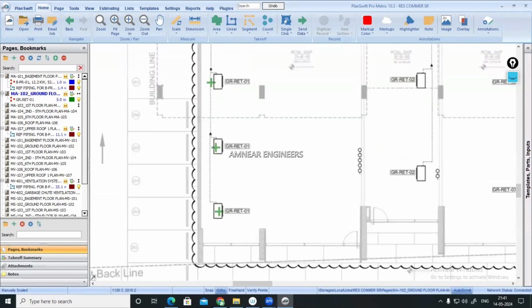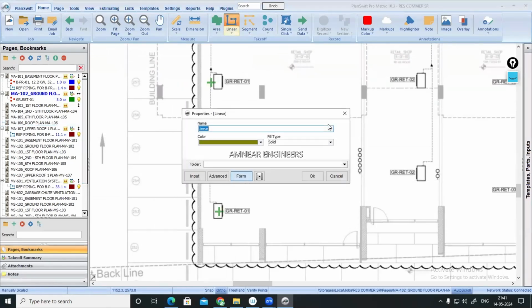Separately we have to, together we can take. Okay. Or for this one, go to linear option. Refrigerant, or even if the refrigerant piping for all the equipments, if you are taking together, then that is fine. But the problem with respect to the capacity, the liquid diameter and the vapor diameter of the refrigerant pipes will not be the same. So that's why, very accurately, normally we have standard rates for these refrigerant pipings and all. So you don't always have to take the refrigerant piping. It is not mandatory, but if you're taking it, how to take it?